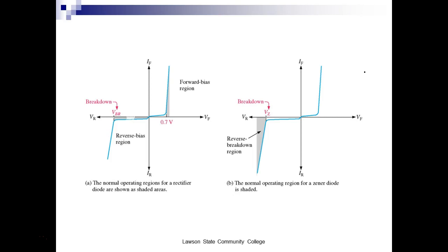If you check a Zener diode with an ohm meter, it's going to check just like a regular diode, so you can't tell it's a Zener diode. The only way you can tell is if you look up the part number. We call this the Zener region, the voltage reference. Now notice it stays fairly constant. It's not constant, but it stays fairly constant over a wide range of operation until you burn it up. And we'll look at how we can calculate that in a minute.